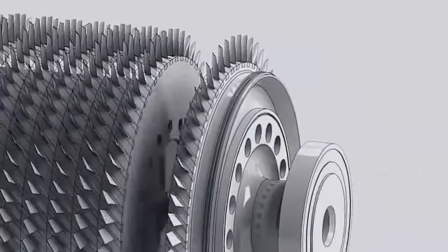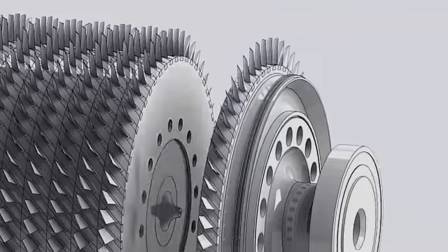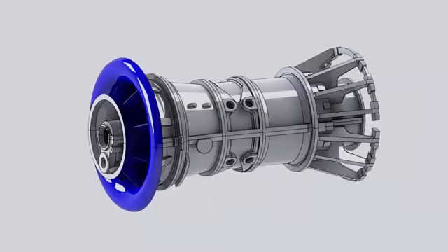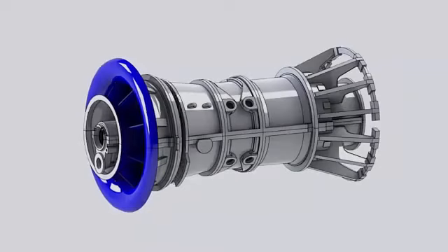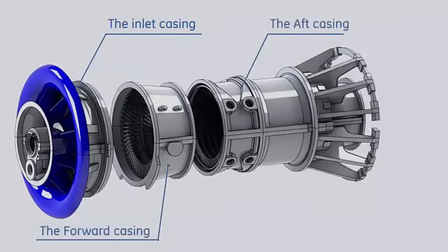The 17th stage blades are mounted on the wheel portion of the aft stub shaft, and they have only forward spacers. These spacers are placed to maintain the relative position between the rotor and the stator blades. Rotor blades are held in axial position by staking at both ends of every dovetail slot. Compressor blades cannot be replaced with the rotor in position. Wheels must be disassembled.